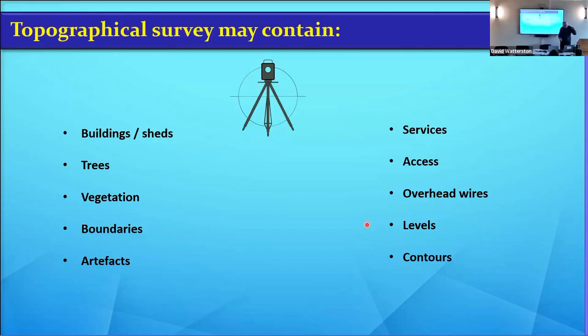So you say, right, I want this level to bring that down to there. I can take that material. So from that point, I need to go down 350 mil. And from that point, I need to go down 250 mil because you've got a good level grid. Whereas if you've got levels outside that, you've got to make some guesstimations. So a smaller level grid, more levels, is quite good.